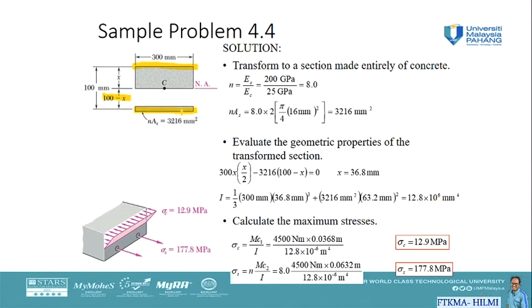And then because now we assume that the steel rod is rectangular, and looking at this result and at the distribution, if we want to simulate the distribution, we are going to find out that the upper part of the concrete is going to carry the compressive load, while the steel rod is going to carry the tensile load.